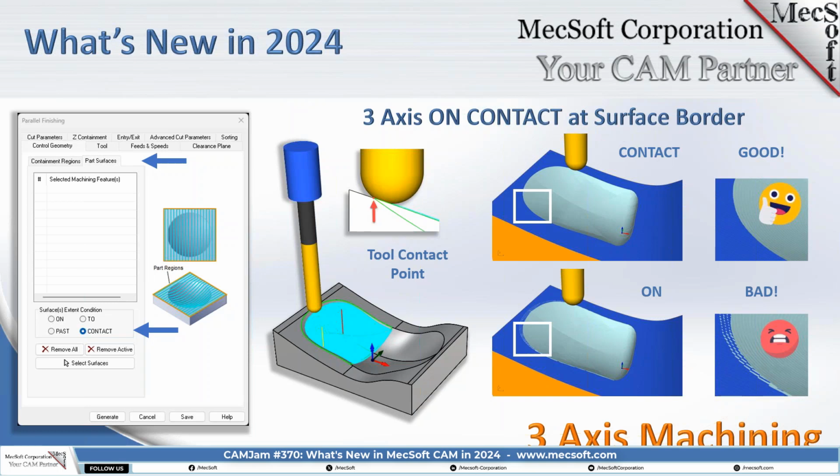You can't let the tool roll over the parting line, because what can happen here, if you look on this bottom view, is the tool, we used the on condition, went right up to the center point, right up to the curve, your control geometry. And what that results in is some overcutting on areas of the parting line itself. And this is just a blow up over here, you can see.